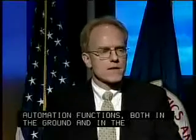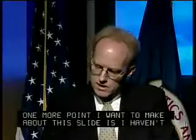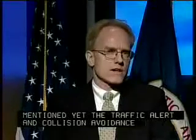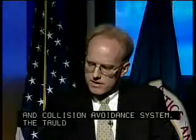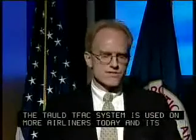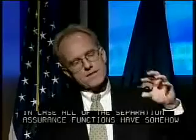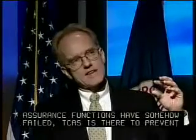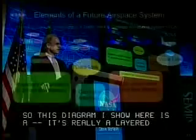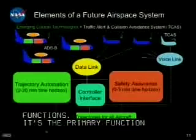One more point I want to make about this slide is that I haven't mentioned yet the traffic alert and collision avoidance system. The so-called TCAS system has been flying on most commercial airliners today, and its purpose is to prevent collisions in case all of the separation assurance functions have somehow failed. So this diagram is really a layered system of separation assurance functions. It's a primary function that tries to solve problems 4 or 5 minutes before they become serious.